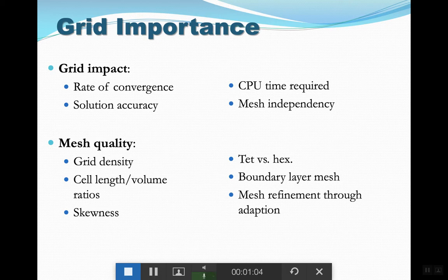So when we are dealing with a big fluid system and we are solving our equations on it, the first step would be to divide this big control volume into smaller pieces, smaller control volumes that are called cells, in order to make our equation development assumption correct. And these small control volumes are called cells, and this process is called meshing or mesh generation.